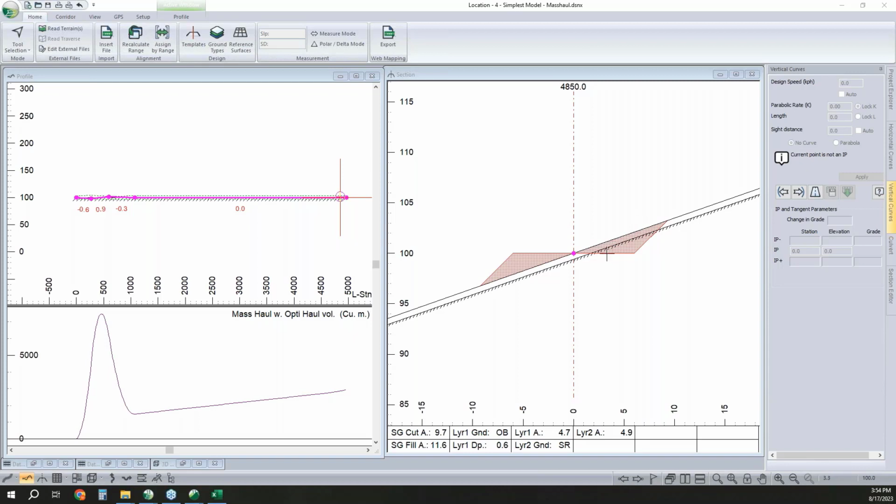If you want to validate whether this makes sense, you can take your road out of location, save it as a terrain file, and do that TIN subtraction in terrain. The two calculations shouldn't be exact, since it's two different methods, but they should be reasonably close. And if they're not, that's an indication that it's worth digging into what's happening.